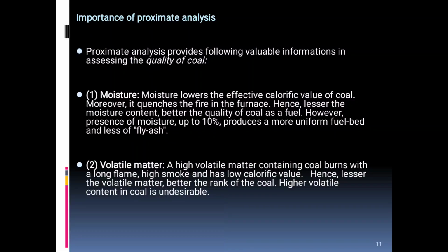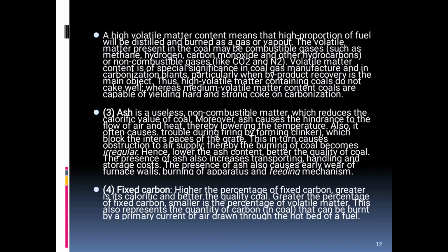And the significance of volatile matter. A high volatile matter containing coal burns with a long flame, high smoke, and has low calorific value. Hence, the lesser the volatile matter, the better the rank of the coal. Higher volatile content in coal is undesirable. A high volatile matter content means that a high proportion of fuel will be distilled and burned as a gas or